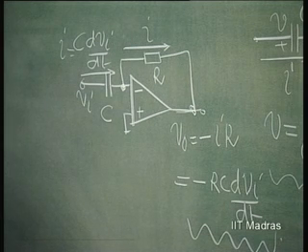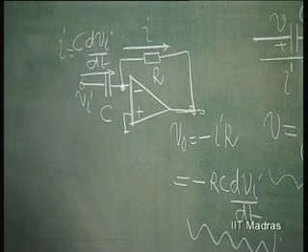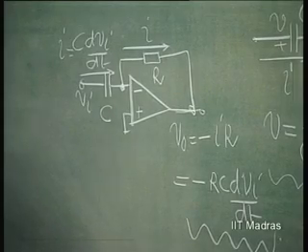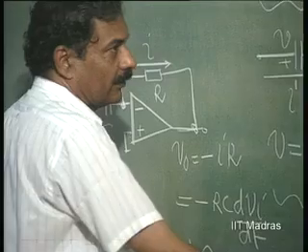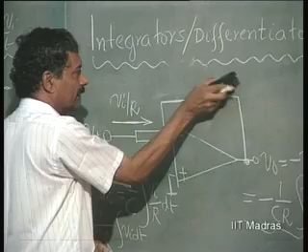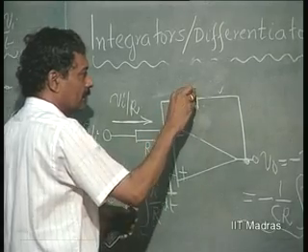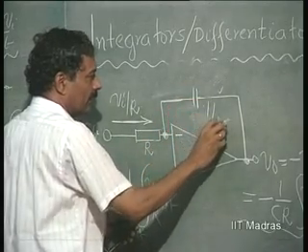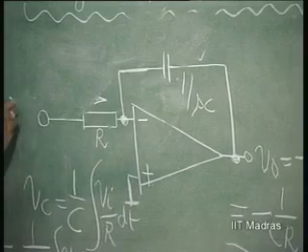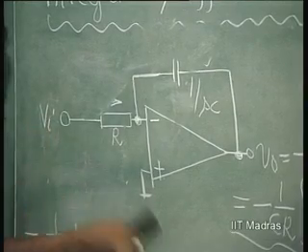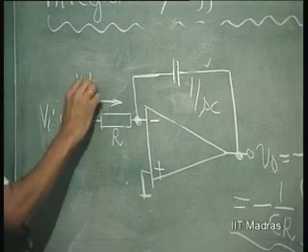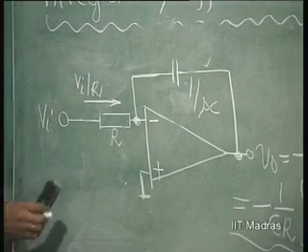Now, what does it really mean in terms of transfer function? This also can be done. Okay. We can replace the time analysis by the frequency analysis here. So, the impedance of this is 1 over S C, and therefore, the same thing is valid here. We have V I now, the RMS value of the input voltage, and the current is V I by R. Okay, that remains the same.